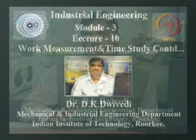Students, in this presentation, first of all I shall complete the remaining portion of the time study, and thereafter I shall take up the portion related to the development, implementation and maintenance of the new method in an organization. So, the time study, as I have said, is one of the work measurement techniques in which time for carrying out a particular job is identified using the stopwatch method, and suitable allowances are added to calculate the standard time and set the standard of performance.